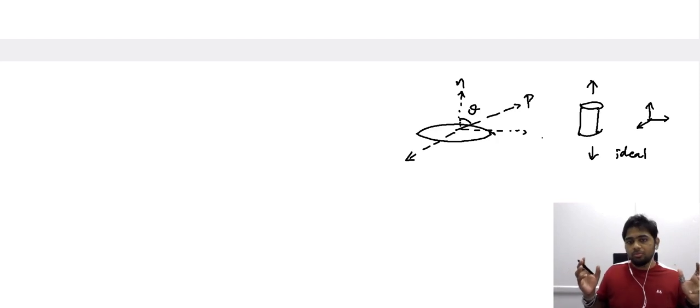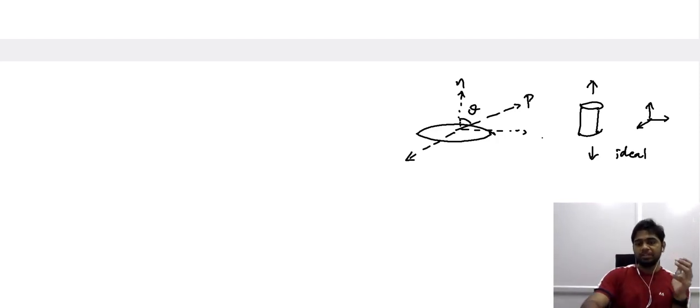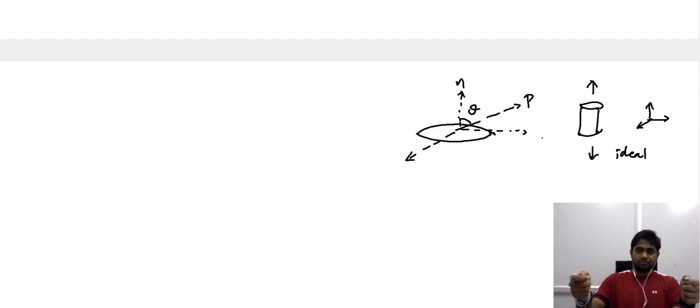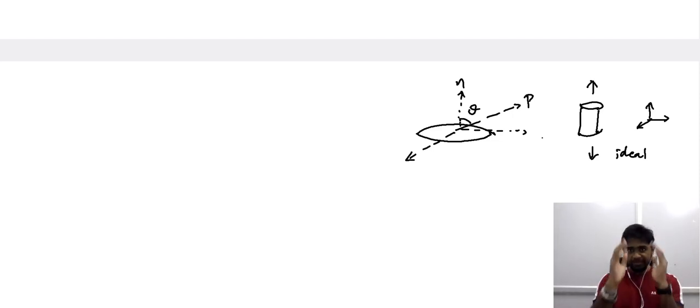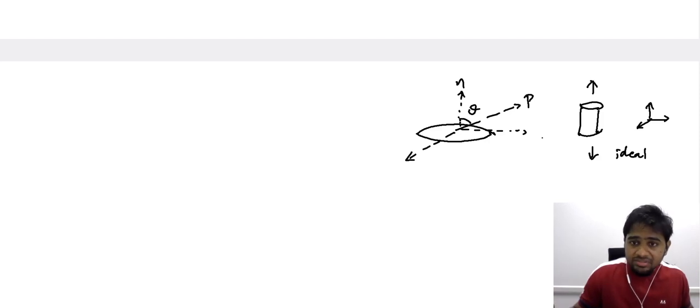Now, in order to describe the mechanical condition experienced by this region of interest, which is experiencing a load in an inclined direction, we consider the normal, the ideal direction along which the tensile load should act, and we can quantify the angle of inclination, which we refer to as theta. When we want to understand how much of the load is experienced along the normal direction, we can project this load onto this direction.